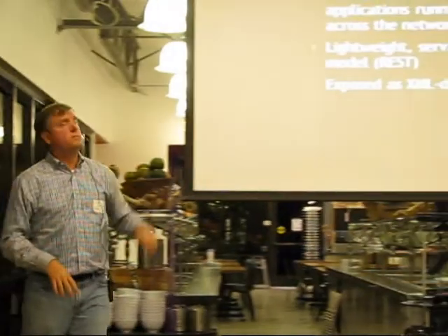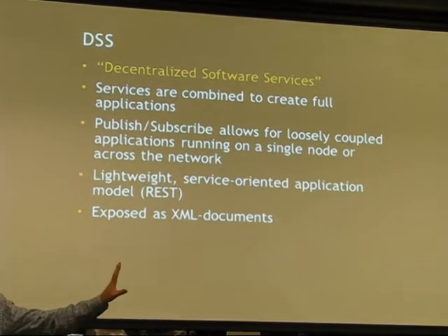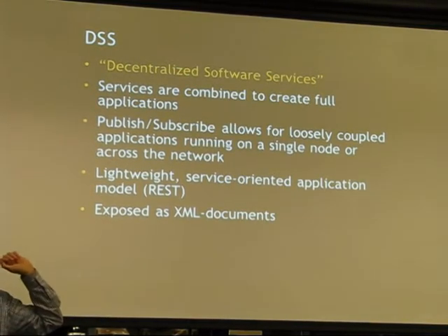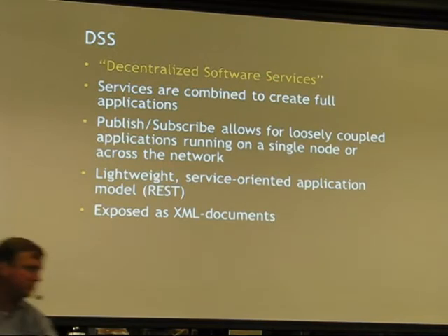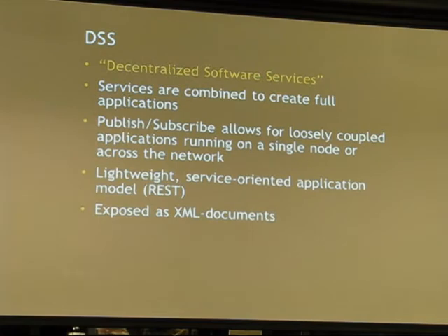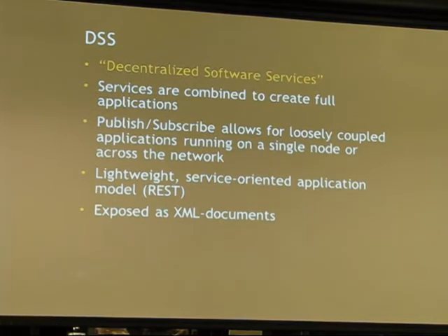Publish and subscribe model, the idea then that I can send off a message to the robot, or some other robot, or another service, and wait for a response, or it can subscribe to me. So I may have a service that I've created for, let's say, an Xbox controller to drive my robot, and it's obviously creating inputs, and somebody wants to subscribe to that. Maybe the robot wants to subscribe to that. Maybe I have two or three robots that are going to subscribe to it